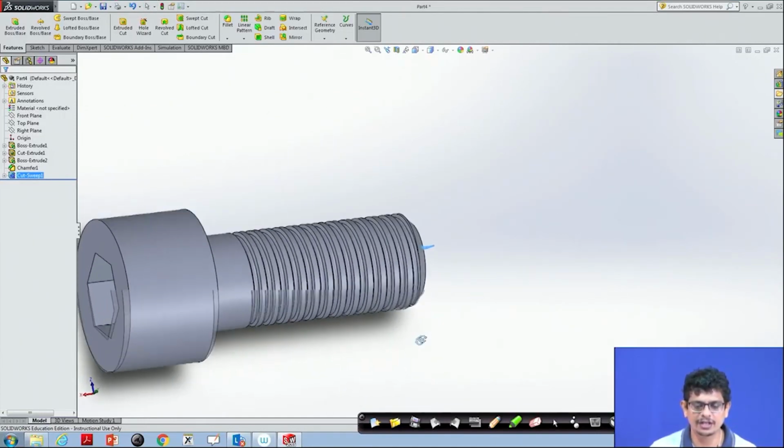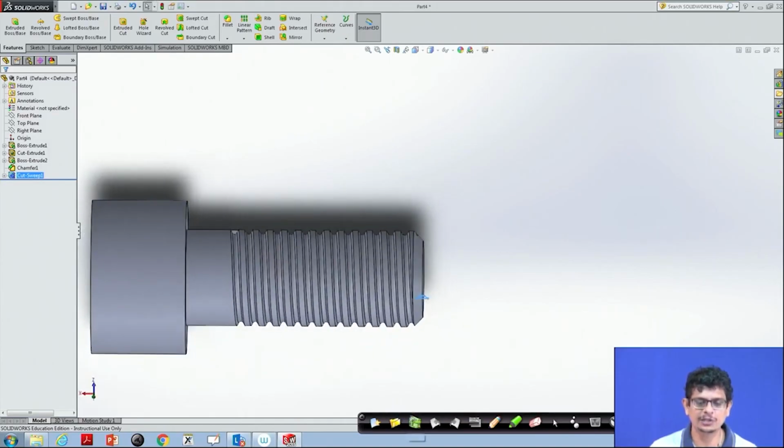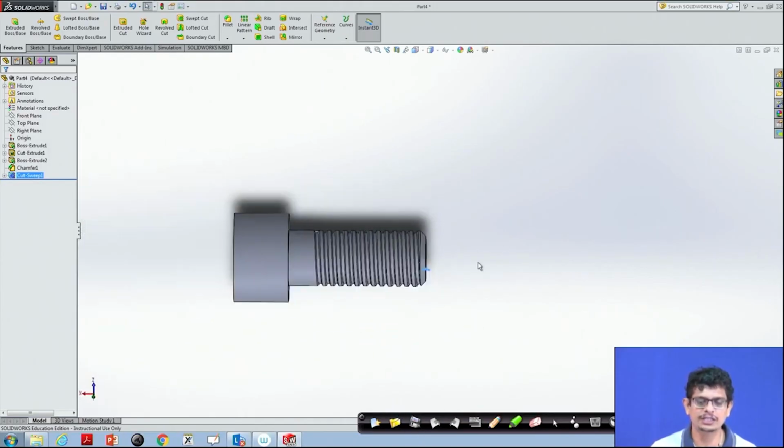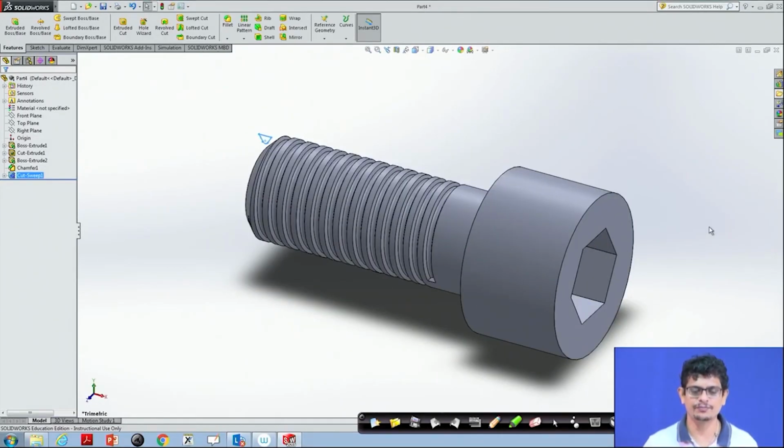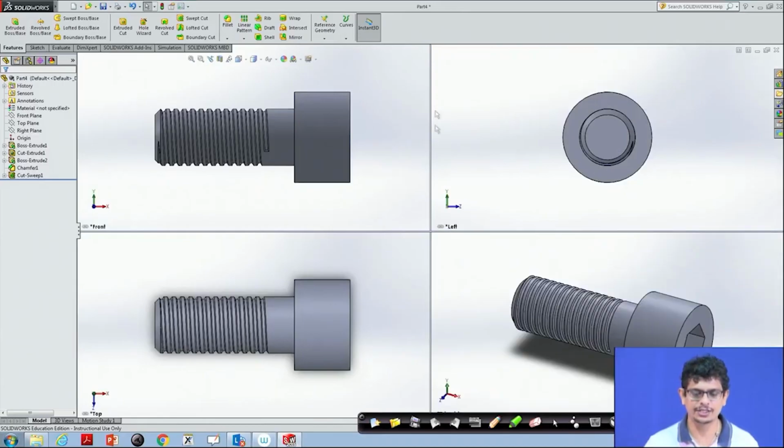whether we can have some other kind of triangular cut and other things. Let us look at different views of this bolt. So, first thing what we will do is look at isometric view. If it is a construction one, we can remove that. So, this is the way isometric view really looks like. Now, look at 3 different views, something like the front view, the top view, the left side view, and the isometric view.